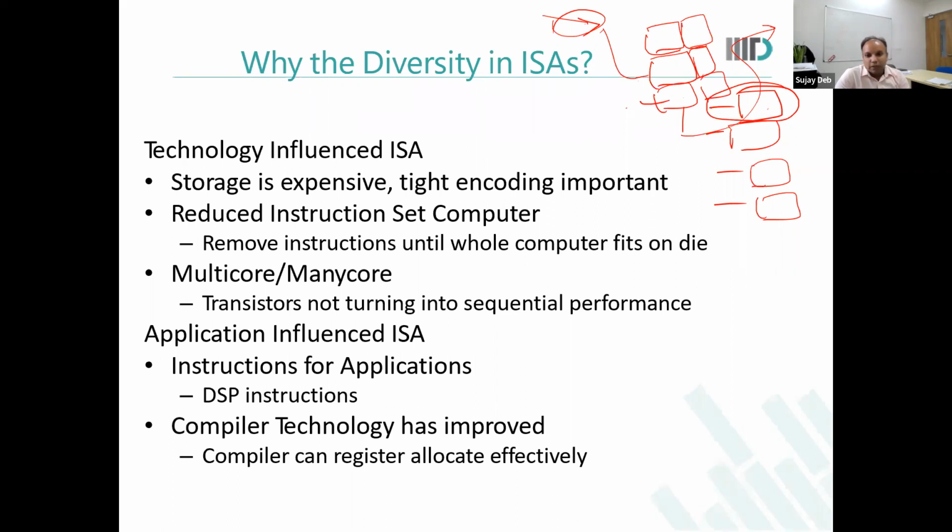So it's definitely not a very good way of designing your processor. The more reasonable way of building this processor is to see whether I can develop some generic hardware and then multiplex those generic hardware units to execute all my 20 instructions. So that will be a more viable way.